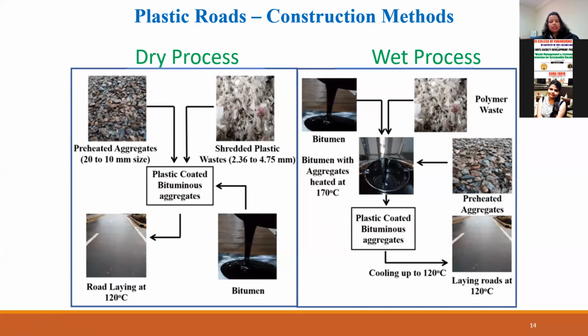So now the bitumen is not going to coat on aggregates and then get mixed with plastic. It's the other way around. So in this process, there is a little difficulty in maintaining the texture and viscosity of the bitumen. And very specially, the rheological research part in determining and controlling the rheological parameters of the bitumen, they require a little more evolution and evaluation both, to be implemented on a large scale.